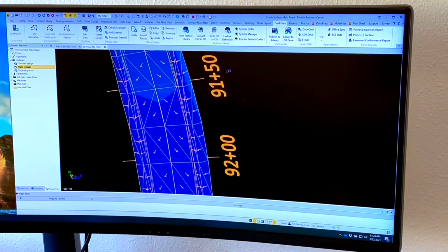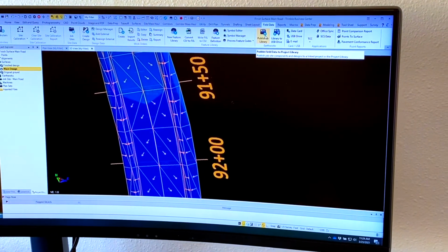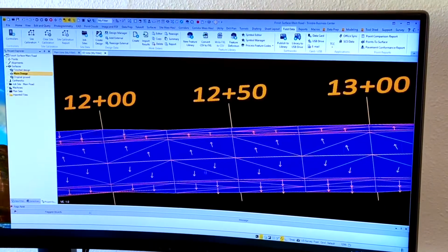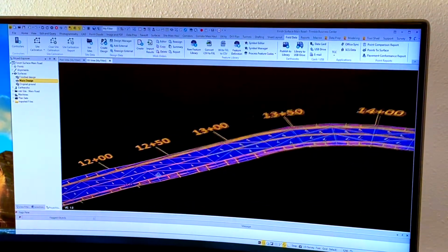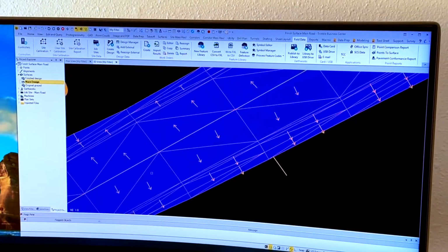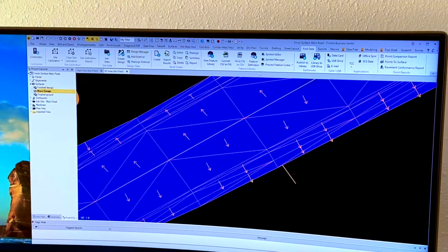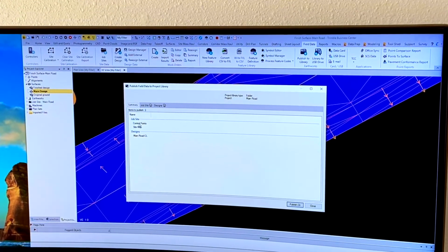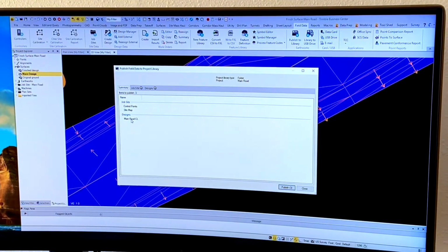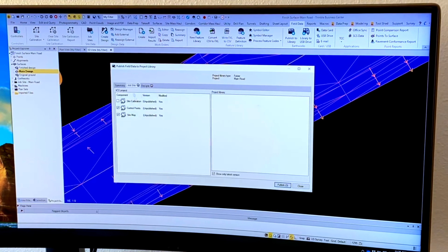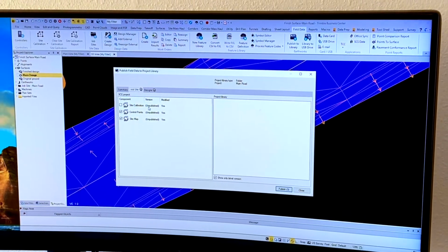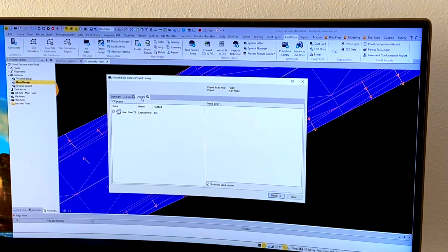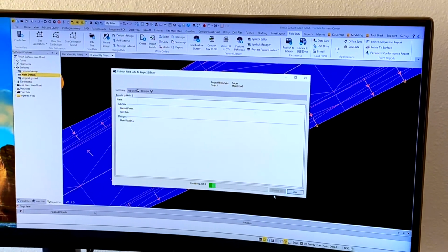Then the next thing to do is to publish this data. So now we have all of our data sets, and we give it one last look to see if there's anything that looks squirrely. So the next thing to do is to publish the data. It's going to give us some control points, a sitemap, an alignment, and the job site. Calibration is already existing because we gave them that previously, and we're going to publish all of this.